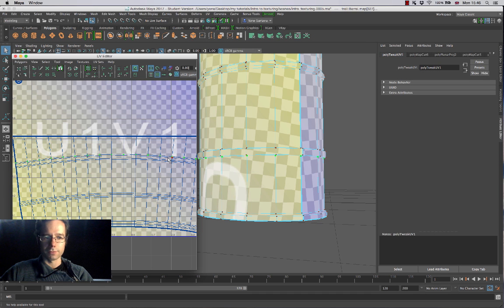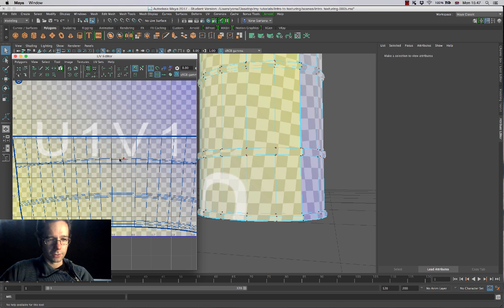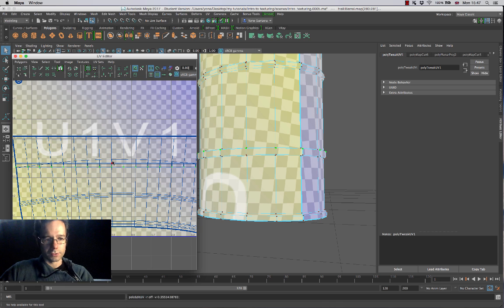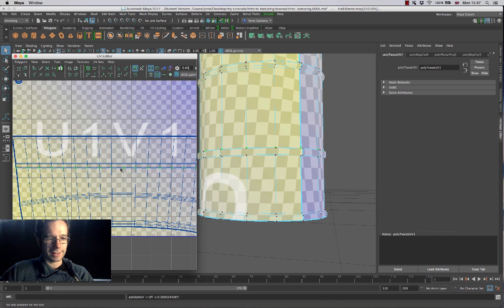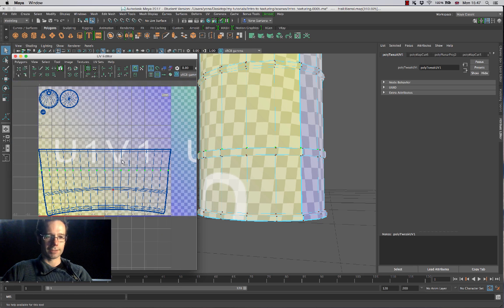And what I'm going to do very briefly is pause the video over here, and I'm going to start basically repeating this align over here and start getting all of my UVs to be in the right place. And you'll see it will just take me a few minutes to do that very quickly by using the keyboard shortcuts, selecting things, and using G to repeat my last command. And then I'll also do it in the vertical as well to make sure that everything's lined up perfectly.